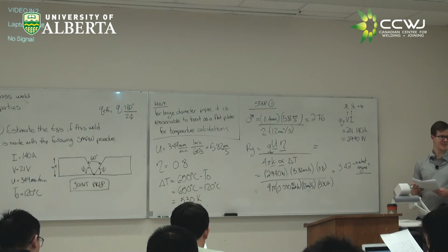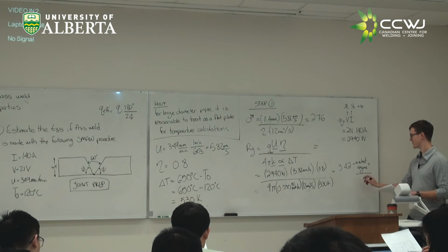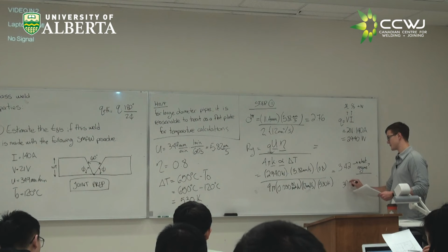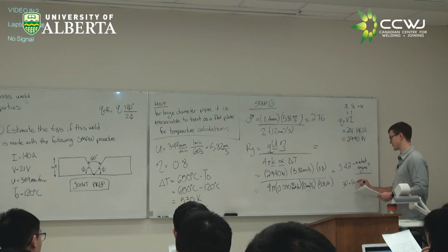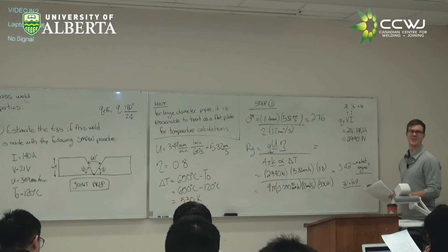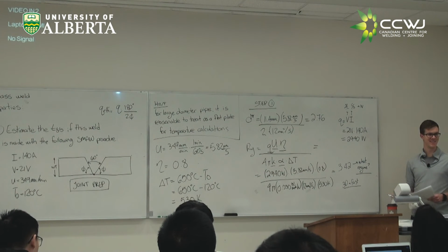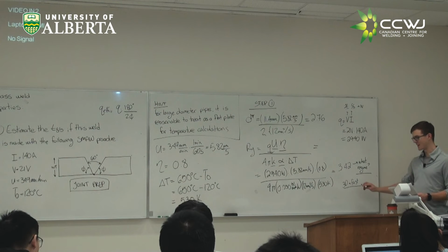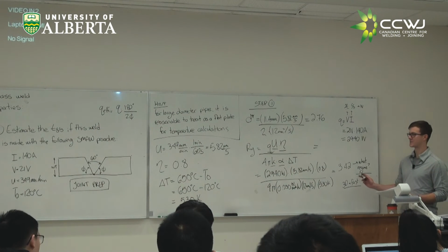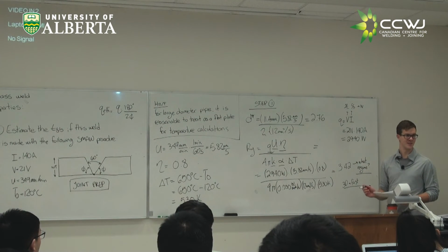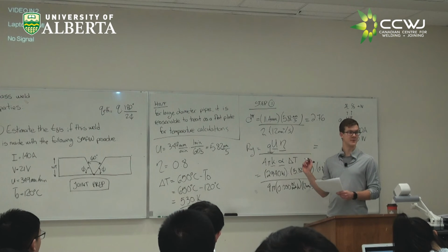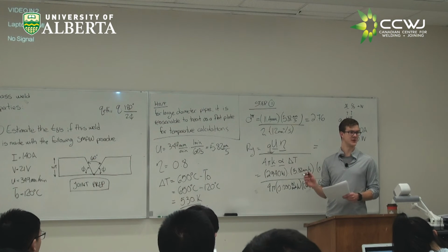Regime 1? Right. I think we get right on the edge of regime 1. So that means we would be using our 3D fast equations. So do we stop here and start calculating? No. Because we got 3D fast, we have to correct for the bevel and recheck it to make sure we're still in the same regime.